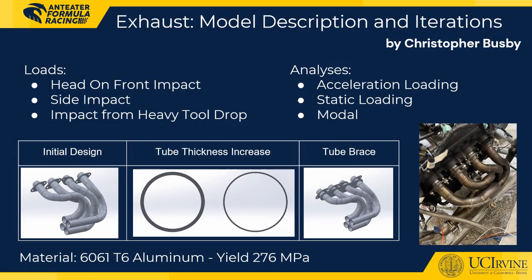The exhaust can see acceleration and static loading, while engine vibrations can cause resonance, which requires a complete modal analysis. The exhaust was analyzed with 3 iterations. One is the original, the second is a thickness increase, and the third is a tube brace.